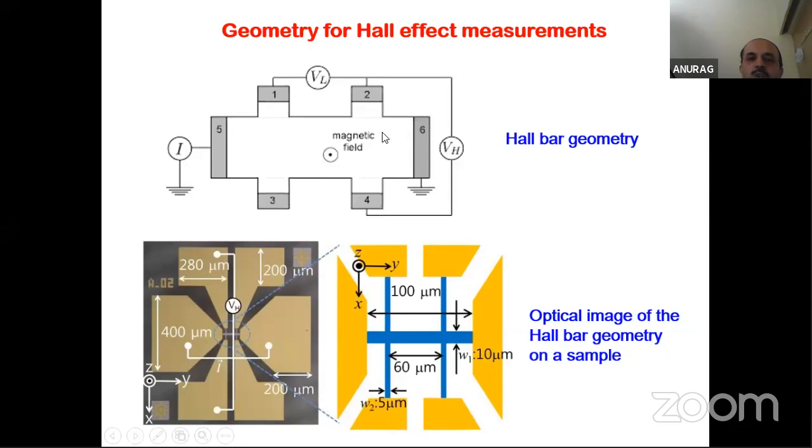So we usually use optical lithography and then reactive ion etching to create this kind of Hall bar structure. What you are seeing is that between 5 and 6, this is a thin film which you have patterned and etched out in this way. So you have the material left only here. Below is the substrate; there is no semiconductor material here. There are ohmic contacts 5 and 6. You flow the current along this direction. So you see it is a perfect geometry.